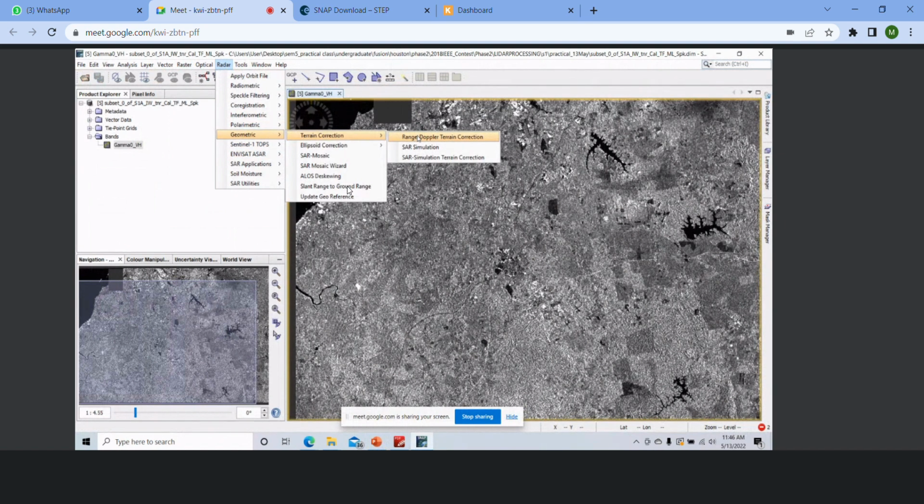So now we need to know that our study area might have different terrains, so there will be some error when the backscatter signal is reflected back to the sensor. So there will be some geometric error, and now we need to process the geometric corrections in this scenario.